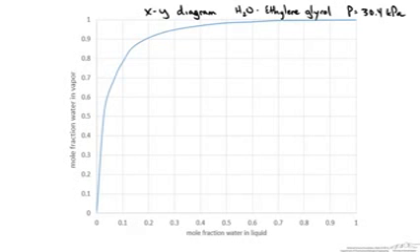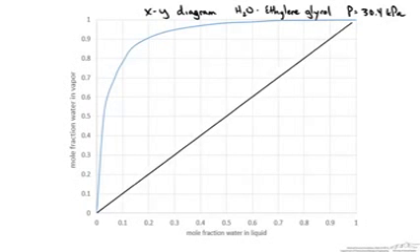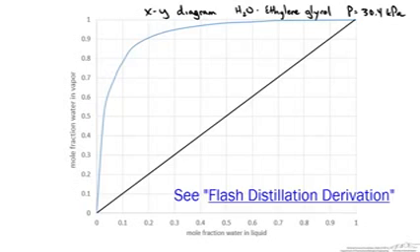This type of plot is convenient because the equilibrium compositions are plotted and can be placed on the same graph as material balance lines, which we'll see in other separation calculations. So we also want to put a y equals x line for reference. This will help us identify azeotropes, where the compositions of the vapor and liquid are the same. Check out our other screencasts on the flash and column distillation calculations so you can see how we apply these plots in practice.